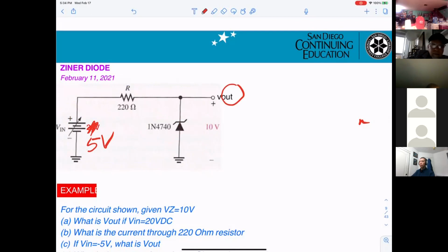You understand, right? Now, in this case, tell me what happened to the Zener. Does it break down, not break down, or is it normal? It's reverse biased, but it's not acting like a normal diode. It is open. They will not break down, right?